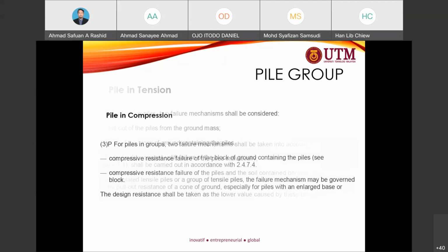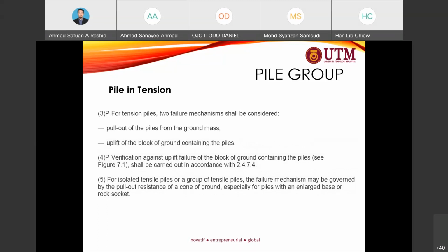Then for piles in tension, two failure mechanisms should be considered: pull out of the pile from the ground mass, and uplift of the block of ground containing the pile. So this is the situation for piles in tension.